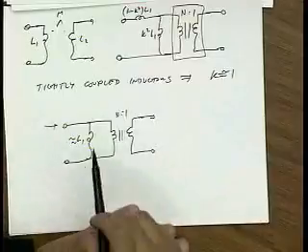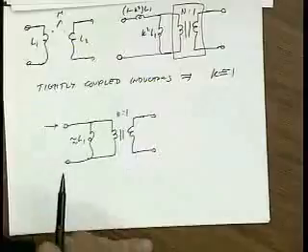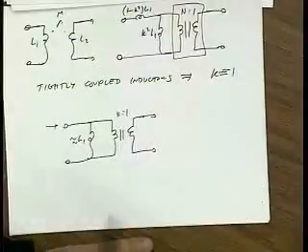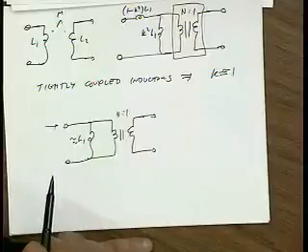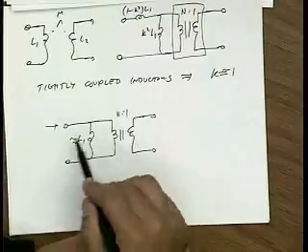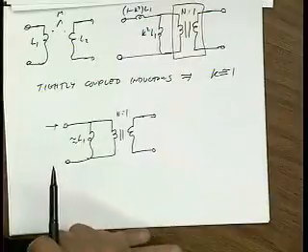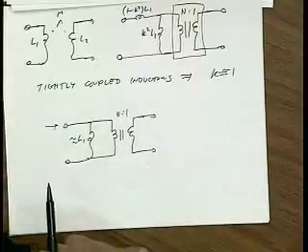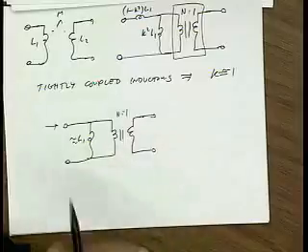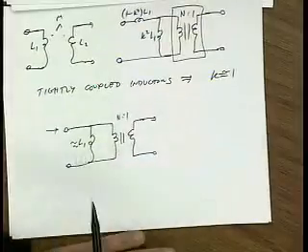But no, in reality, there's a cutoff frequency. There's winding resistance, and so you get a cutoff frequency. And so you can show that there's actually a transition frequency. You have to be above that transition frequency for this to work. So to push the transition frequency lower and lower, I have to make this L bigger and bigger. And that's why low frequency transformers are huge. They're physically very large to get very large inductance. They also use magnetic cores to boost the inductance.